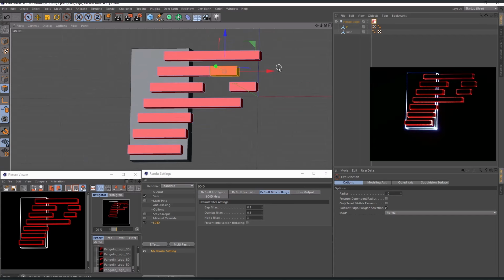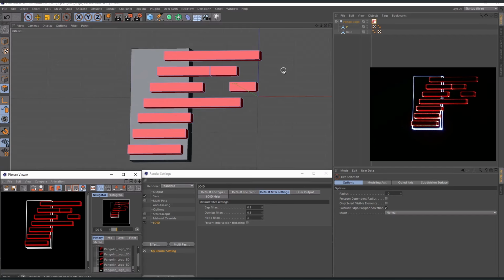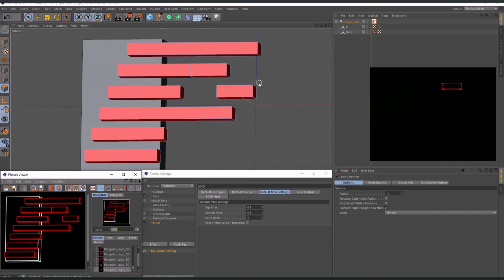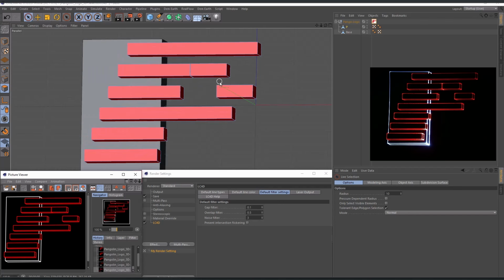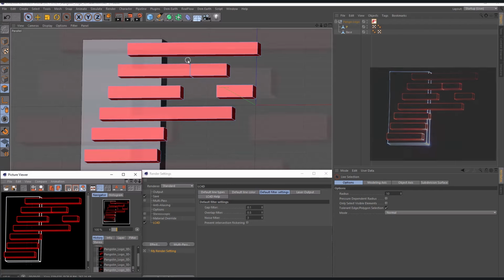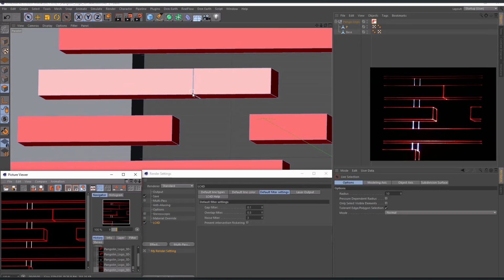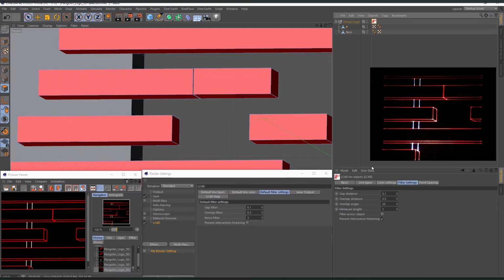And if I render this object now, we'll see that there will be two lines visible very near to each other. And in reality, those two lines will be hardly visible on your screen. So this might be a chance to reduce points. So let's see how we may save some output points to reduce flickering of the laser graphic. To try this filter function, we simply need to increase the value of gap distance.